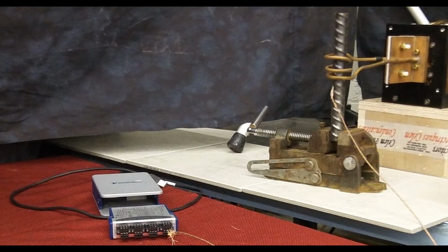In today's training video, we're going to connect the optional data acquisition module to eVIEW. The data acquisition module is an accessory that allows the customer to monitor 4 external analog signals. Those analog signals can be 0 to 10 volts, 4 to 20 milliamps, thermocouples, or RTDs. eVIEW will take this external analog data and integrate it into eVIEW. So it will show it graphically, and it will also store it in timestamped spreadsheets.